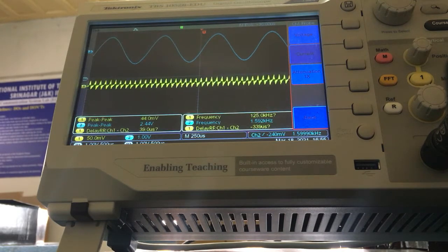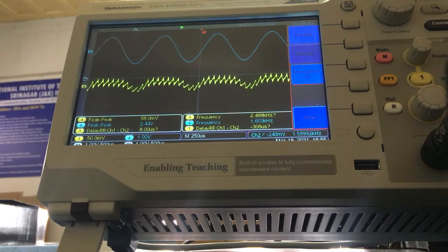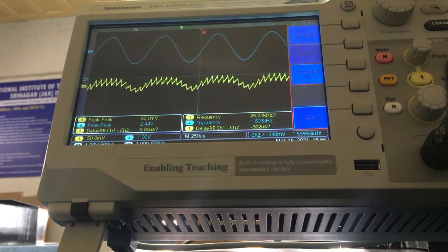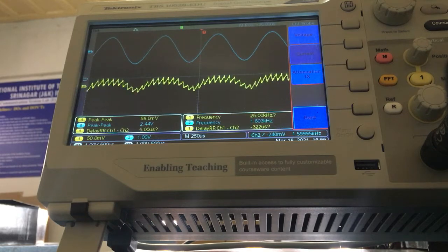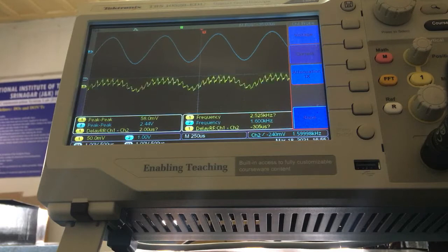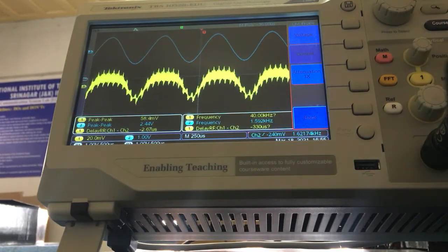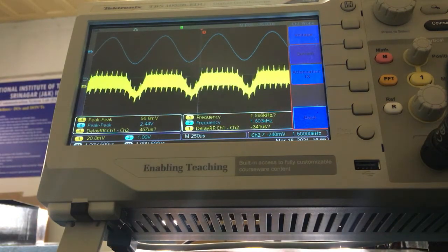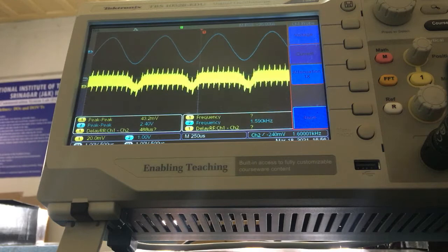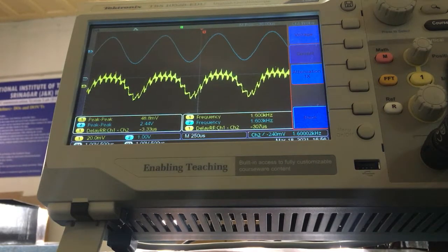Essentially it won't follow the signal, because there's a trade-off with the time constant, which changes because of this. Maybe you can increase the scope scale to see the change I was talking about. If you reduce it, it won't follow the signal. If you increase it to the maximum, you can see it follows the signal, but still there are some excursions.